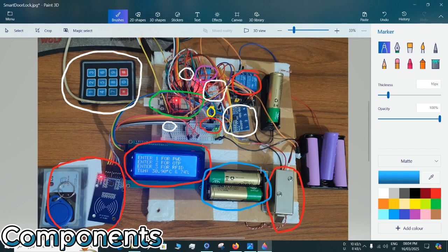So I have to step down the generated 8 volts to 5 volts, and in order to serve that purpose, I have used the LM7805 linear voltage regulator that steps down 8 volts into 5 volts, and the generated 5 volts is thus supplied to the appliances like the DHT11, the LCD display, and the 2-channel relay module. Over here you can see that I have a battery pack of 3 cells which is used to power the solenoid electric lock. So I believe that I have described all the components that I've used here.